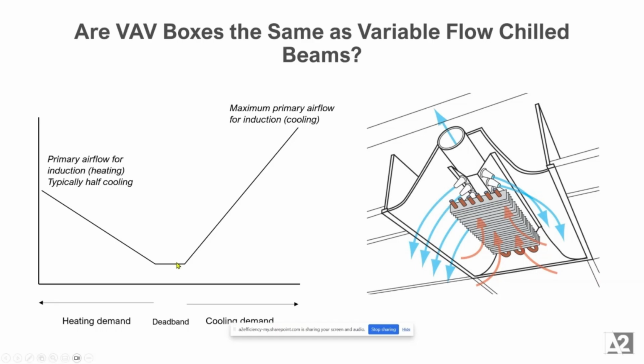And it was actually more static. This line was lower down here, right? It was in ventilation, but the second it went into cooling or heating, it would jump. Let's say ventilation was 0.2 CFM a square foot, it would jump to 0.3 at the smallest inclination of cooling or heating. And so we ended up modeling that, right? We ended up saying, look, you're actually going to have more outside air. It's still variable, so it's better than a constant flow induced chilled beam.